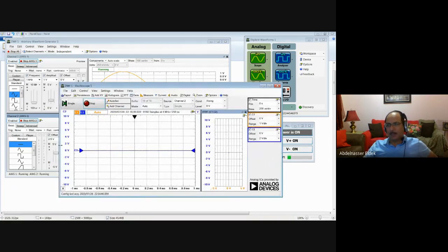So we will explain the oscilloscope later on when we have some devices like, for example, when we have AC signals and so on. But in general, in the oscilloscope, we have time. This is the x-axis, and you have channel 1. You see, this is the orange one, and you have the blue one, which is channel number 2. And you can select the offset and the divisions. For example, here you see 2 volt per division. So each division has 2 volts, 1, 2, 3 volt, and so on. You can change that. For channel number 1, it is only 1 volt per division.